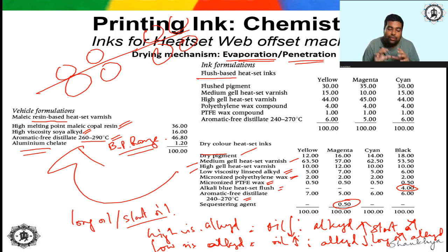It should be able to hold the ink onto its surface and ensure a smooth, uniform layer of that printing ink, and transfer it to the next roller. But this is only possible when it is deglazed, that means when it is a relatively rough surface, with peaks and valleys. If these peaks and valleys are covered by these materials, then it will not be able to hold that ink and transfer it to the next roller. That is the problem actually.